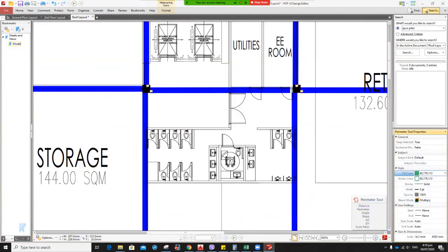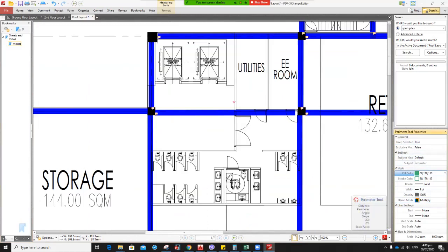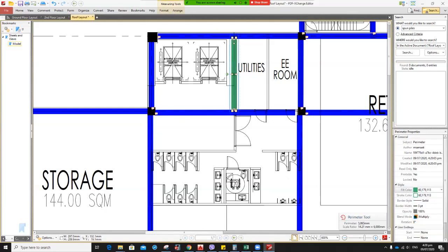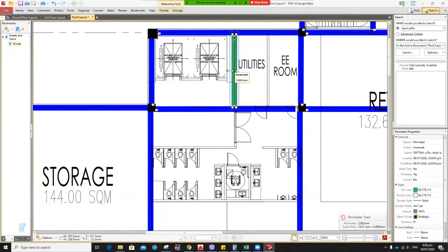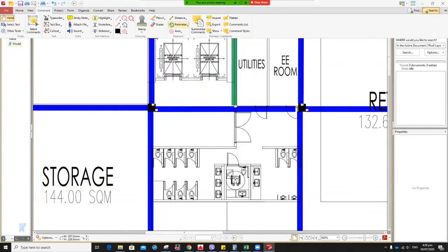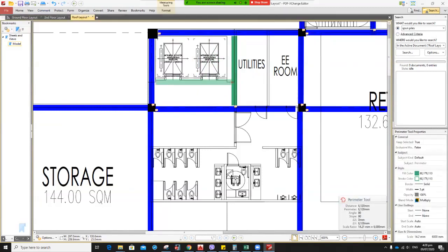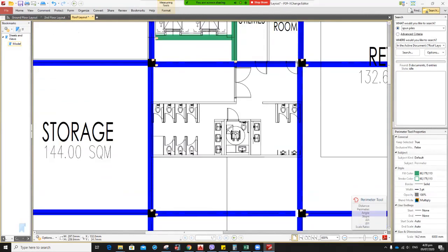Okay, so we will be putting here, for example, on this one, we will be needing an intermediate beam here. Yes. And this one. Sorry, I think better to just draw it. So something like that. Okay. Also on this one, due to the toilets, these walls might be very heavy.